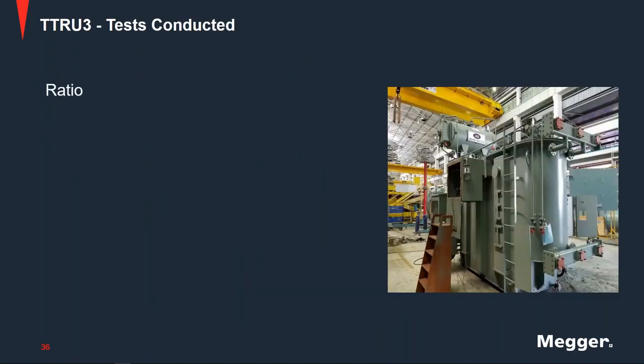Some of the tests that are conducted with the TTRU3: while it is a true three-phase device, we can test single-phase switched if needed. If you want to try and match results to your historical results, that is why we have it. And also, not every transformer is going to operate 100% correct all the time. If you have a damaged winding, then you need to be able to excite one phase at a time to determine if the other two windings are still functioning or to try and isolate that problem winding.